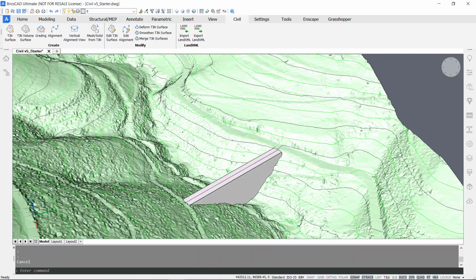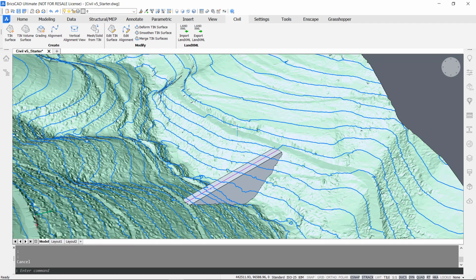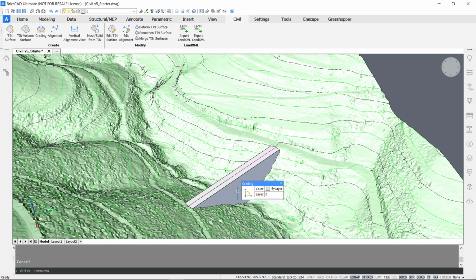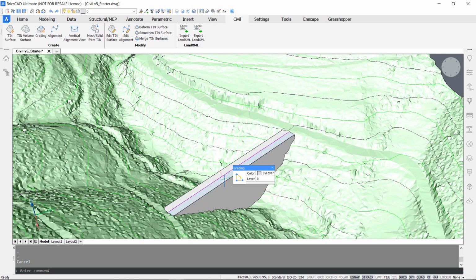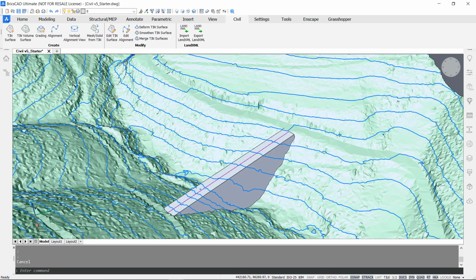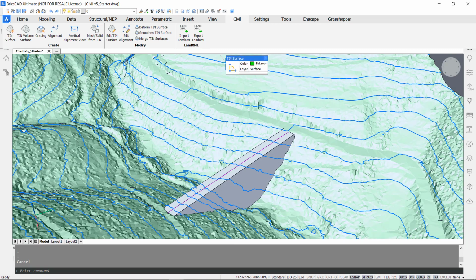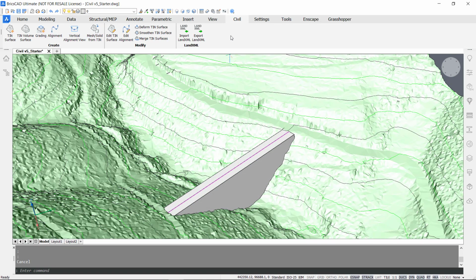All right, so this is the final dam accumulation geometry and location that I want. So like this, I can finish up by merging all the 4 gradings. So now my dam here consists of 4 gradings, but let's make it into one surface so it's easier to control and also easier to get the right information out of it.